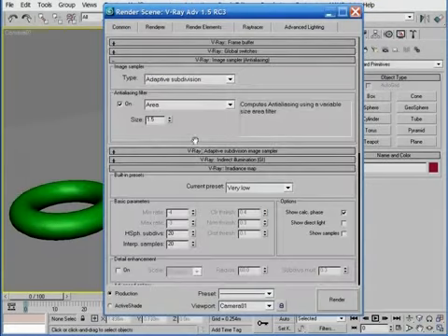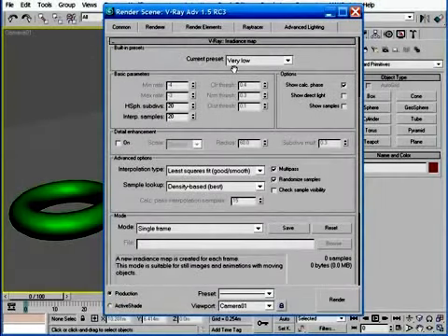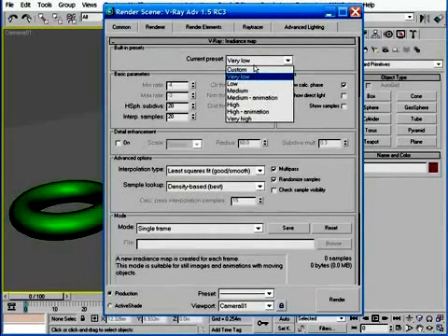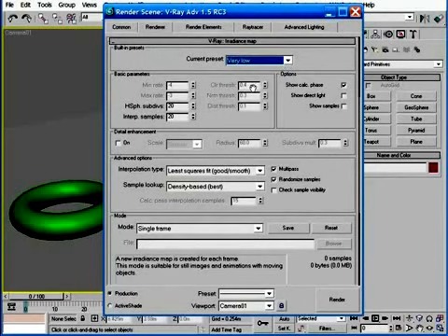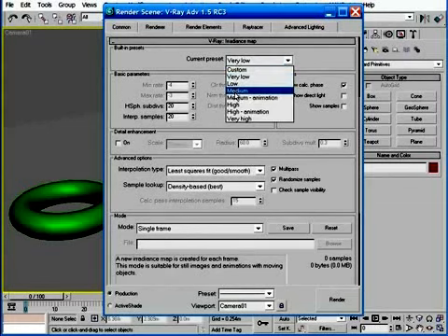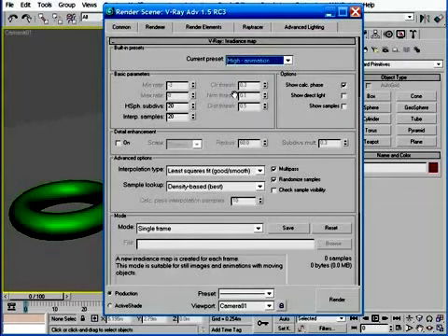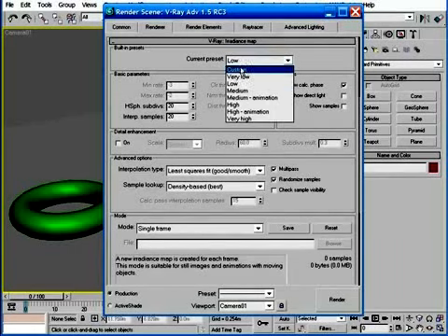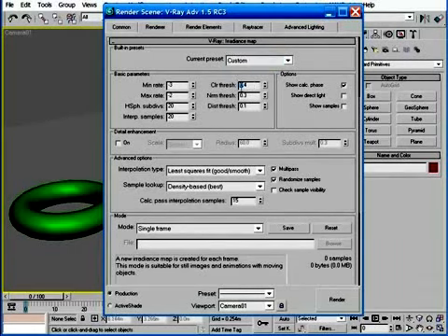And when I do, you'll see some values that are different from the default value. At the top of the Radiance map rollout, there are numerous settings that control the samples and the number of passes, and thereby controlling the quality of the final rendered output. And at the very top, you'll see some presets. These presets control other settings down in the basic parameters section. And unless I have the custom preset set, I cannot even change individually the settings that you see ghosted out in the basic parameters section.